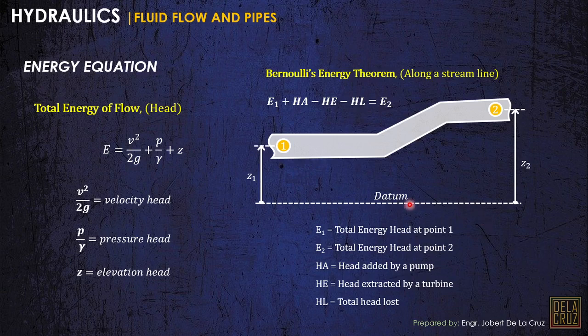So, the total energy in fluid mechanics or hydraulics, we denote that as energy head. Yan yung ginagamit natin dyan, the energy head. As we all know, energy is expressed in units of kilonewton-meters, pound-feet, diba? Energy is like the unit of a moment, force times distance. But in hydraulics, most commonly yung energy natin is expressed as head, into unit distance, meters or feet, mga ganyan.